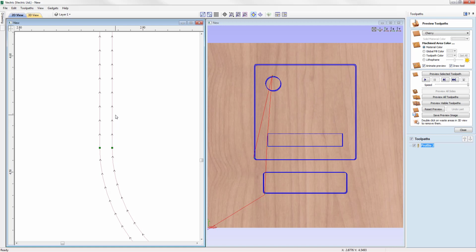And so what it does, it uses more of the length of the cutting teeth to machine away the tiny amount of material that is left on for the last pass, and we reduce the amount of witness marks on our part. So you need to be aware that the tool you are going to use has cutting teeth at least equal to the full depth cut. Otherwise you may risk the tool and the machine damage from forcing the tool shank into the material. And this really is a nice feature to use to create nice clean cuts.